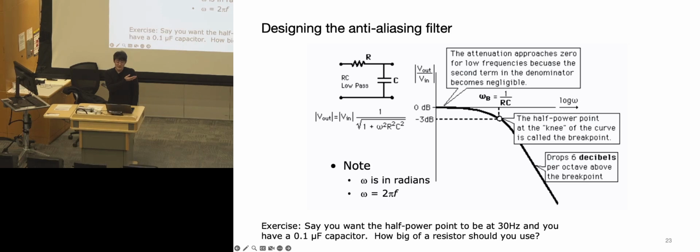They're not perfect. So basically, the cutoff frequency is usually determined by the dB of the signal, essentially meaning how big this signal is compared to the rest of the signal, usually used to calculate the signal to noise ratio. So for example, we usually characterize the cutoff frequency as where it's below -3 dB.